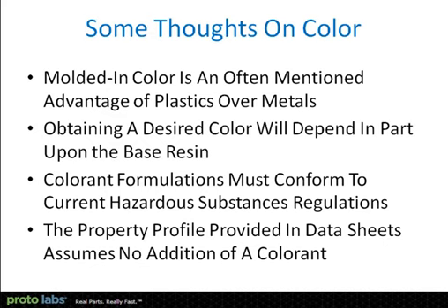What I want to start out with is just some considerations for thoughts on color. Molded in color is something we often mention as an advantage of plastics over other materials, metals specifically. Certainly ceramics, wood, all these things have to be painted in order to achieve desired color. And although there are certainly a significant number of plastic parts that still get painted, most notably in the automotive industry, even there, the desire and the target is to get to a point where a Class A finish can be achieved in an as-molded part.